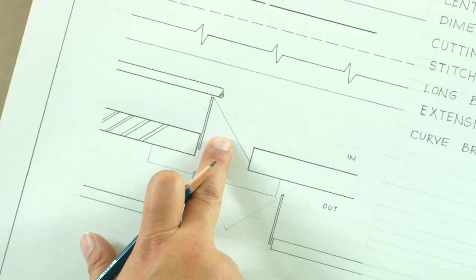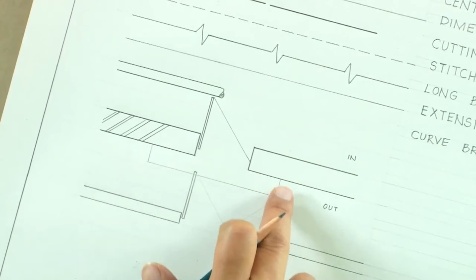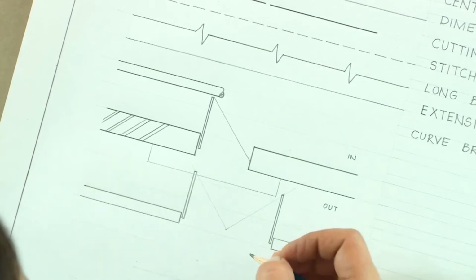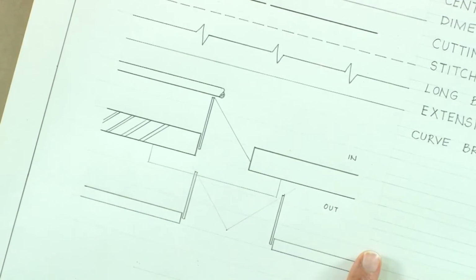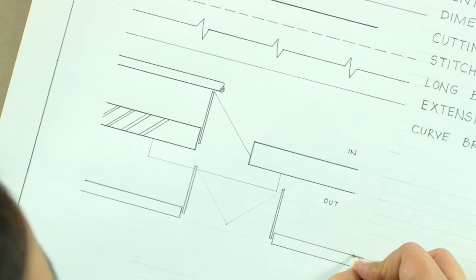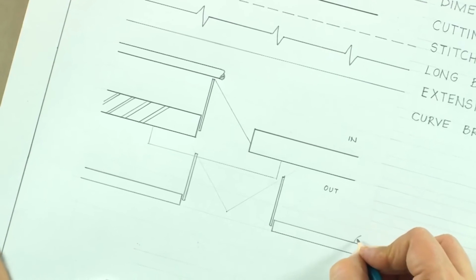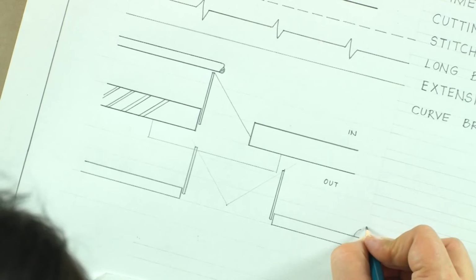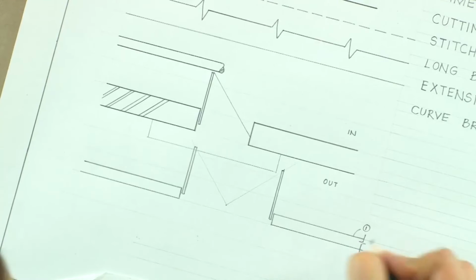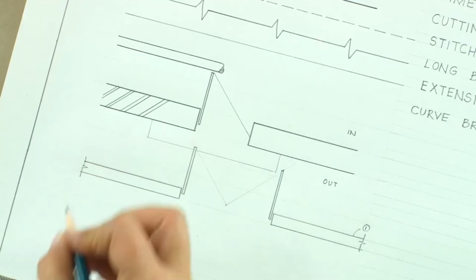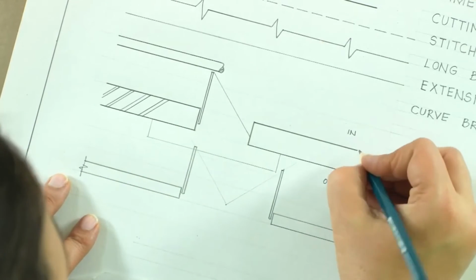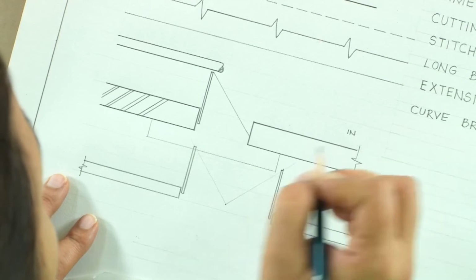So this is a single door only inside, single door outside. This is the representation for a double door which is opening like this. And when you are drawing this kind of drawing, please mind the level of darkness. This line is going to be the darkest. If I write in a descending order of darkness and thickness, this is the darkest because this is brick in section. And please remember that you will have to draw section lines on both ends of the brick. So you will draw section lines on both the sides, whether it is here or wherever.